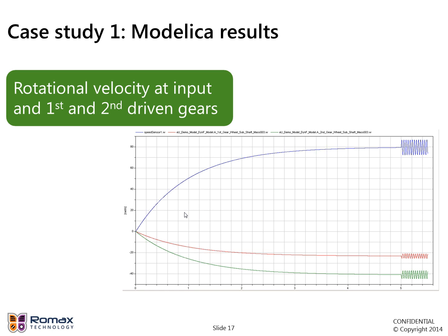So to look at the rattle behavior, what we're doing here is we're going to drive the input at a particular velocity. We start at 0 and we ramp the velocity up to a particular rotational speed, and then once we've reached a certain speed, we start inputting a vibration into the system to simulate an engine vibration coming in to the gearbox, and we see what happens with the gear rattle. So the blue line here is the input. So we've ramped up to a particular speed, 80 radians per second here, and then we start exciting it here.